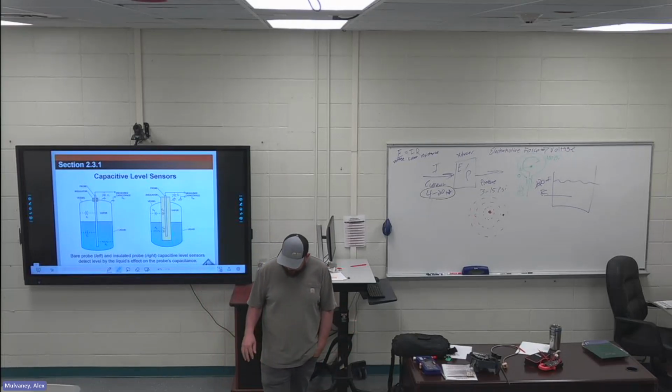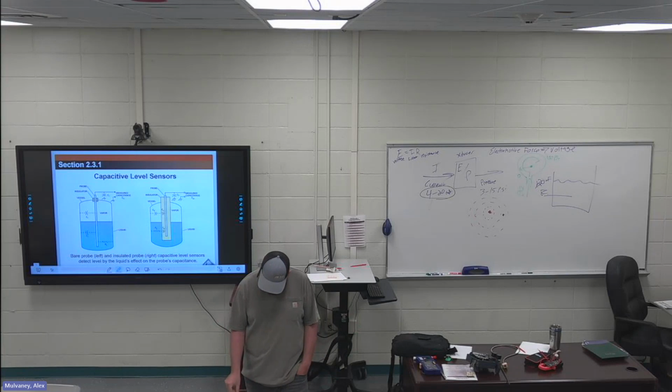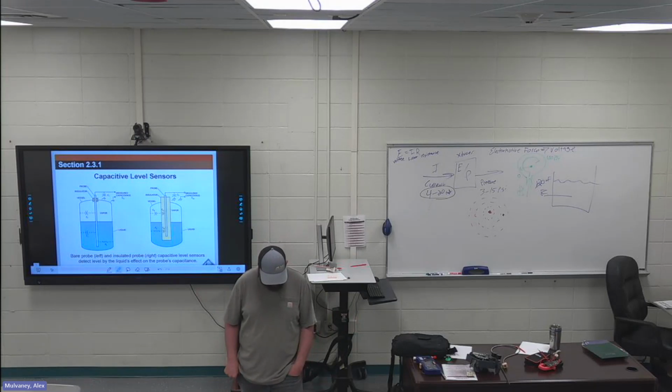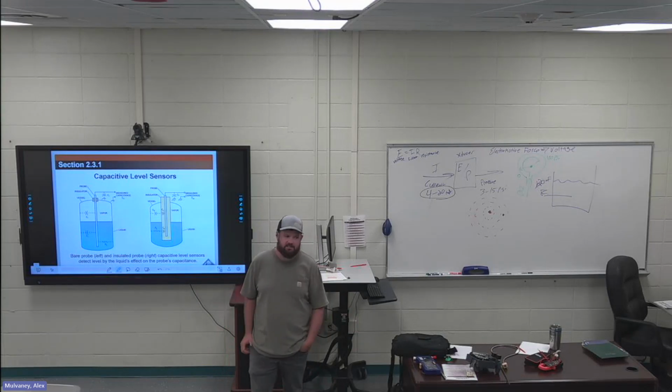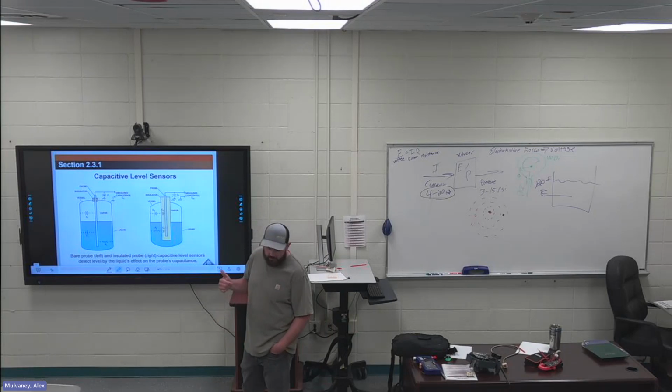Ultrasonic level measurement. My highlight for this is the last thing on page 27. Secondly, and more significantly, the velocity of sound varies with temperature, atmospheric conditions, and the composition of the liquid. Since measurement accuracy depends on knowing the actual sound velocity, ultrasonic level detection is suitable only for installations where those conditions are relatively constant. Mostly, ultrasonic is going to be in an enclosed tank, right?